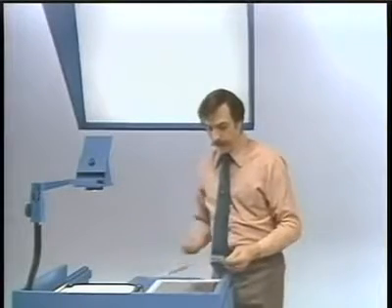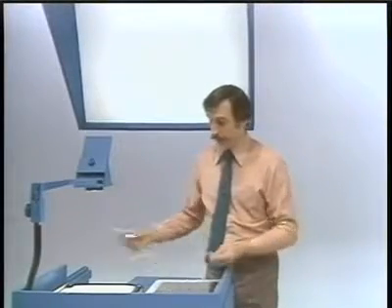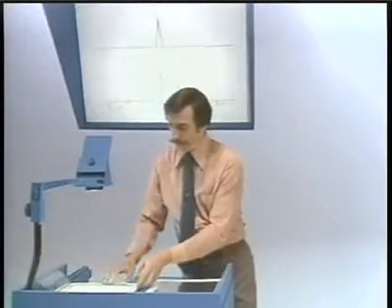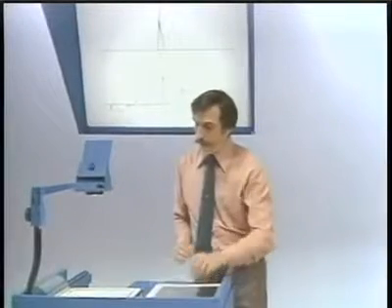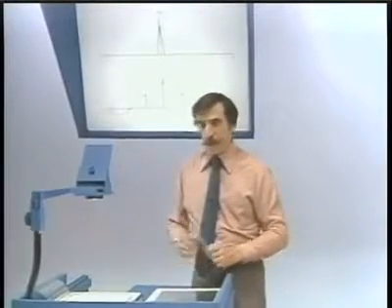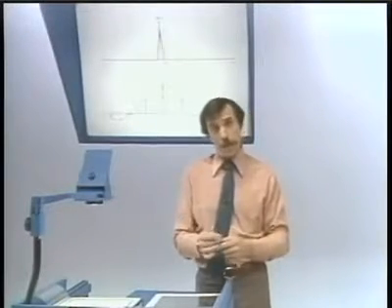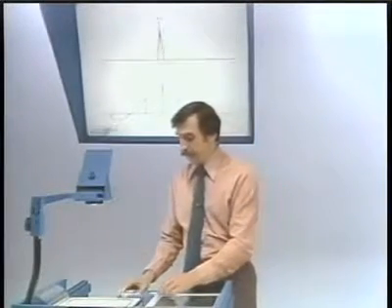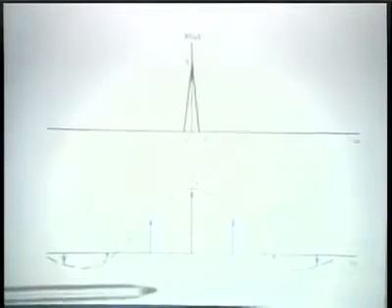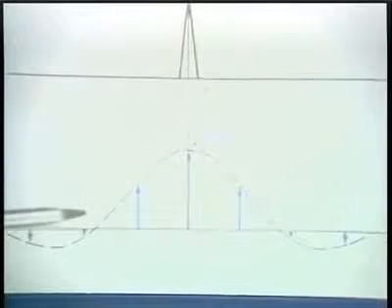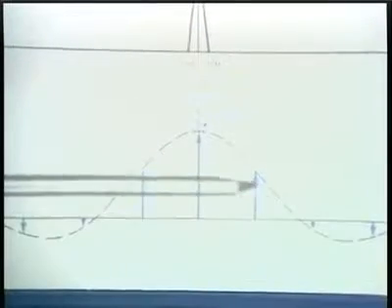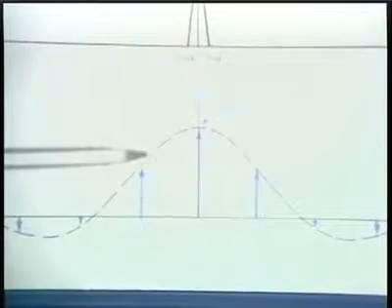Okay, let's see how we get the basic result that we want to get. What we have is a modulating signal which is a pulse train, basically a square wave. And as we've seen in previous lectures, the spectrum, or Fourier transform, associated with that is an impulse train. And the envelope of that impulse train is of the form of a sine x over x function.